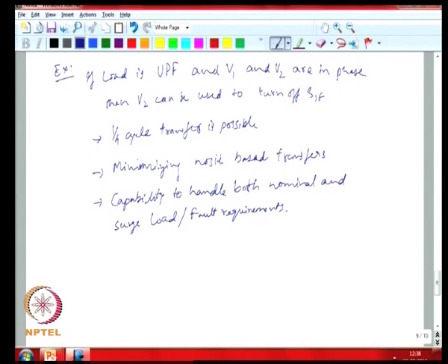So, designing these transfer switches is quite challenging. If you look at the design of a transfer switch, you have 2 sources. People also talk about static breakers. Here you don't have an alternate source to help with your commutation, which means that it is even more challenging.